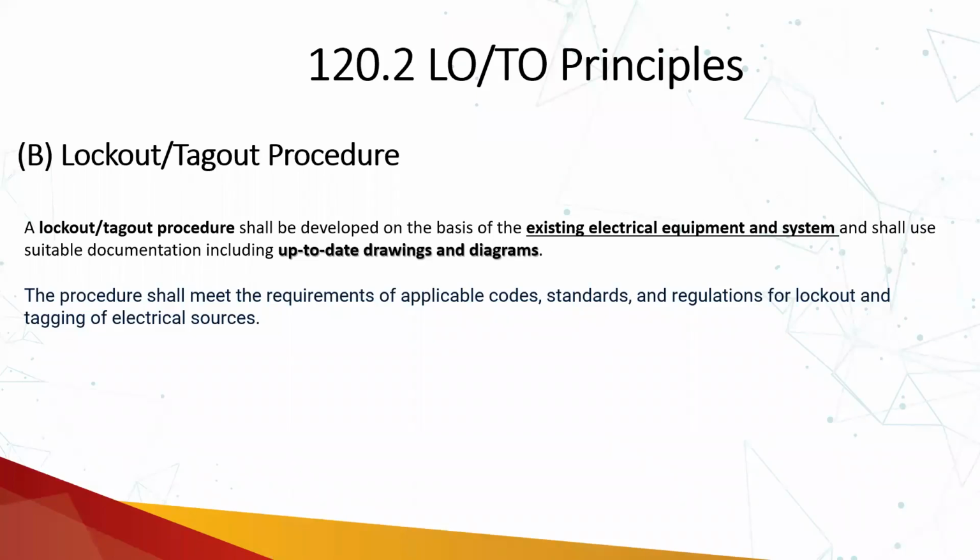If there is some development going on, new substations are being constructed, etc. So those situations used to change very fast. So it's a very important thing that you should keep your single line diagrams up to date.